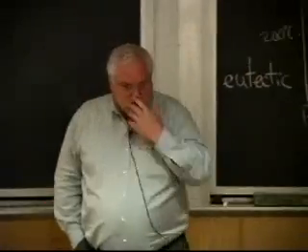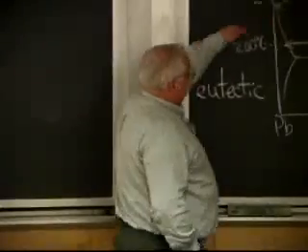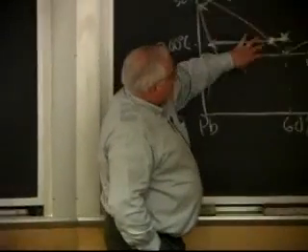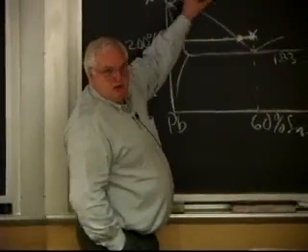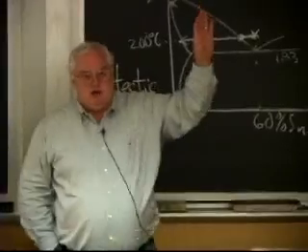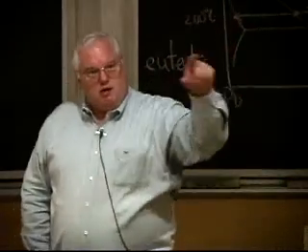It means low melting. There's also peritectic, which, if this thing, instead of going down when I alloy two things together, went up, you'll end up with a peritectic phase diagram. And peri means the same thing as perimeter. And basically, peritectics tend to segregate on the inside.